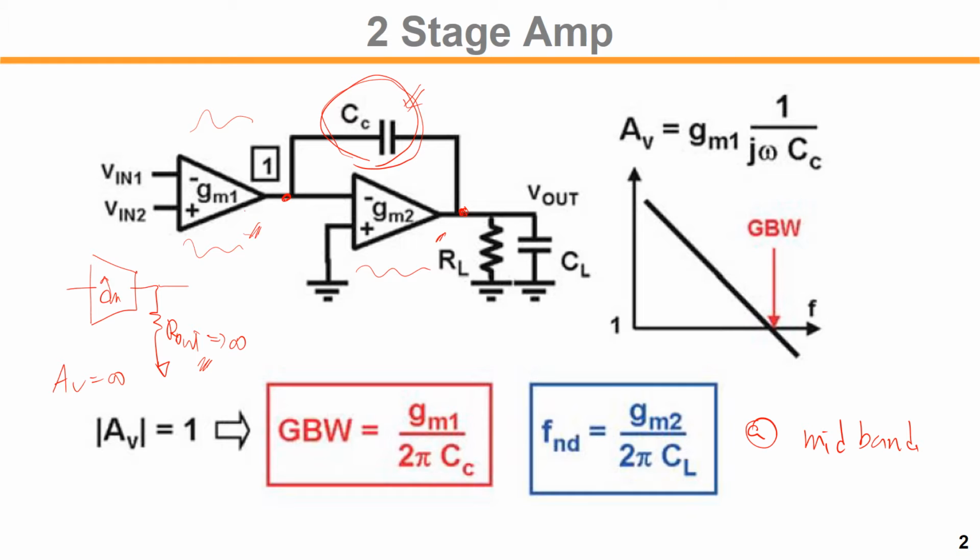With the Miller effect, we know that a small voltage variation at one terminal will appear as an amplified version of the voltage on the other side. So the effective capacitance will be boosted by the voltage gain. That's something that we learned about the Miller effect, right?